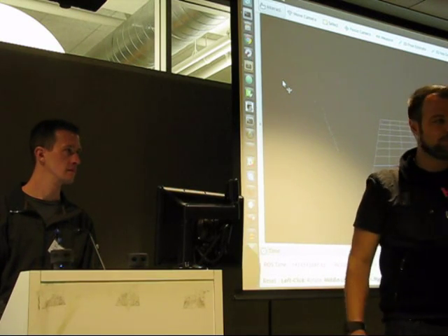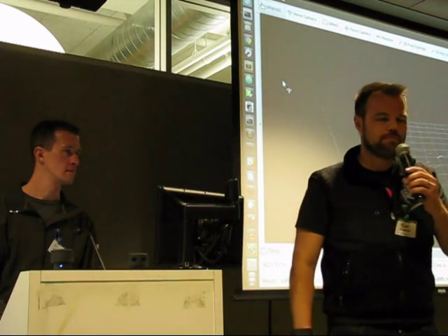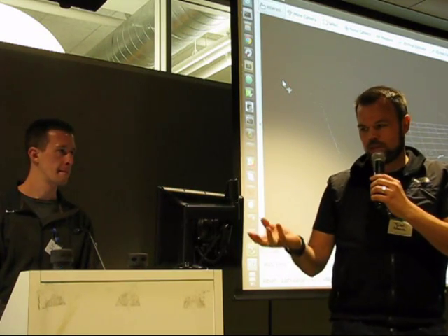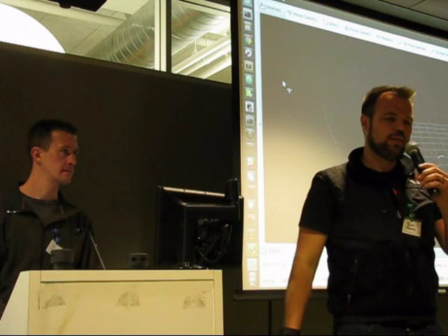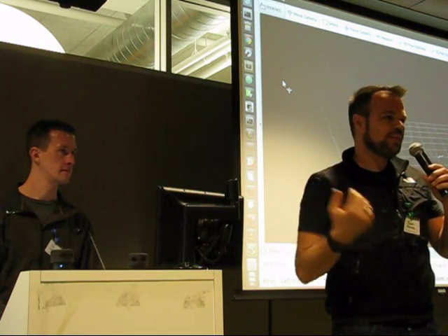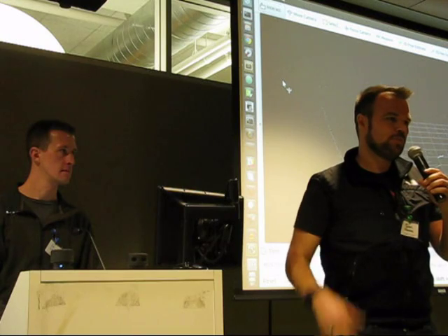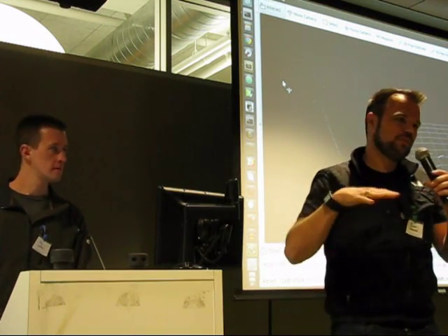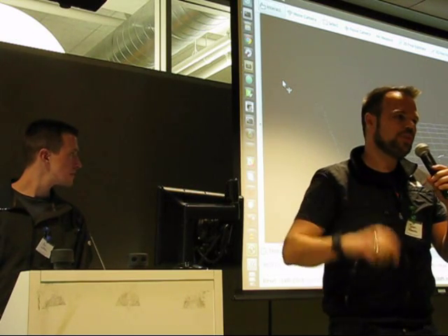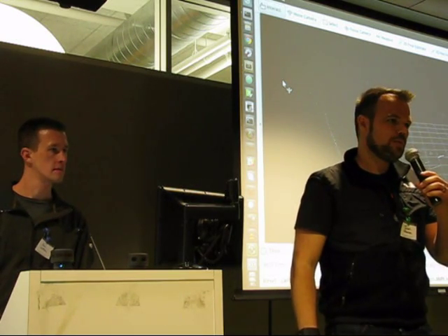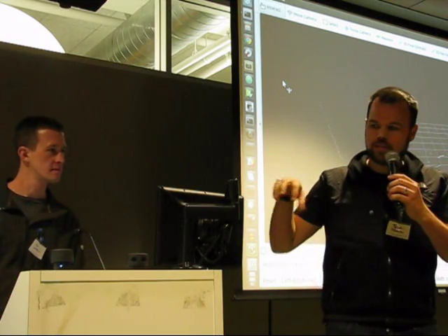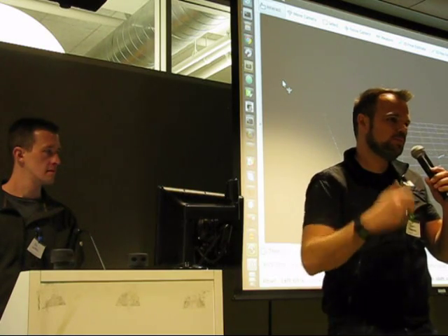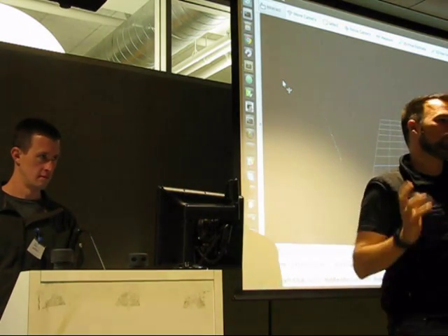So it's pretty sturdy. It's really designed for moving mobile robot applications. Of course, it's got a head that spins, so if your robot's doing lots of spinning, that can affect it some. If your robot's mostly doing X, Y, Z movements, and not too jerky, then you shouldn't have a problem. The head is dynamically balanced, so as long as it's being moved in X, Y, Z motions, it won't affect it.